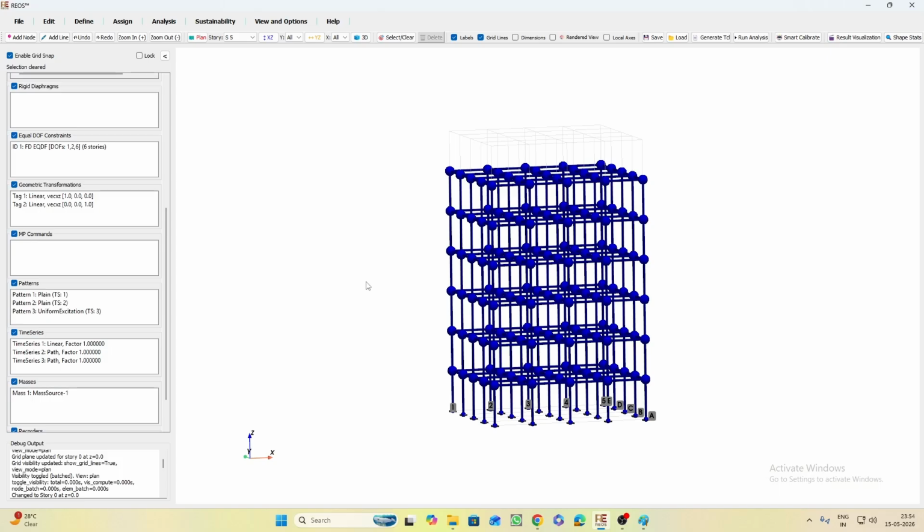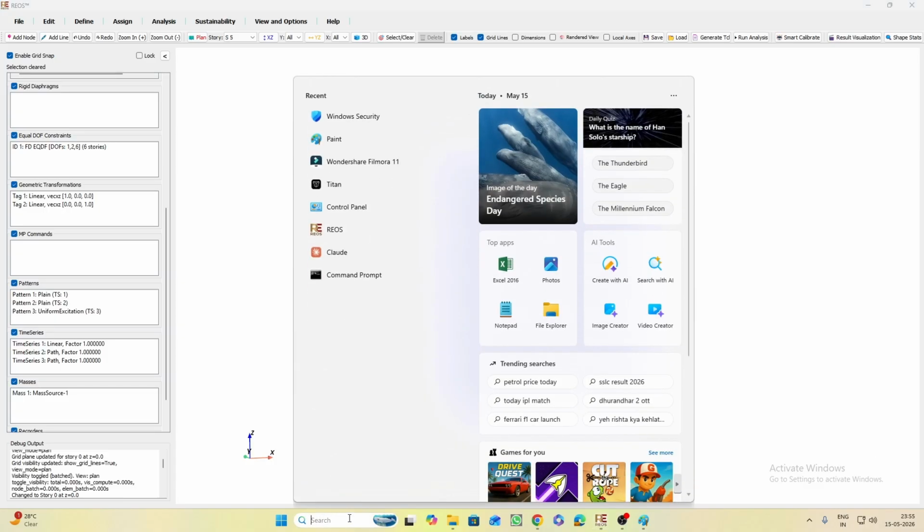Again, one more important thing is you cannot randomly decide this one. The shape will be decided based on the modal analysis. In this example, we are not going to carry out the modal analysis. If modal analysis is run, then we definitely have the mode shape known, and we can take the same mode shape and apply the load accordingly. But for this example, we'll assume a mode shape instead of running the modal analysis first.